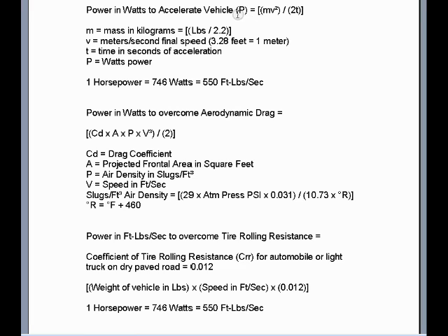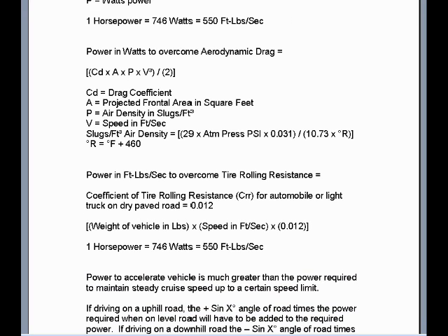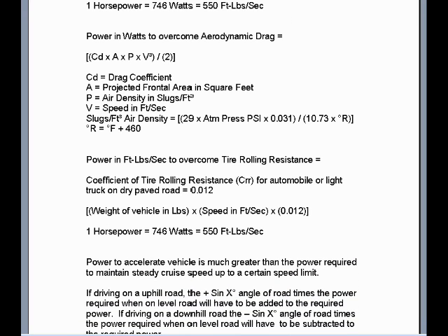When calculated correctly, the watts power to accelerate the vehicle will be known. That is then divided by 746 watts, which is equal to 1 horsepower. So now you've gone to a final speed after acceleration. Now you're at steady cruise speed, no acceleration, no deceleration.